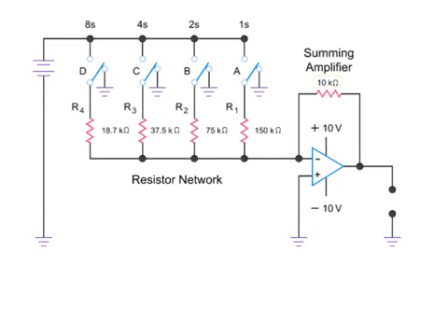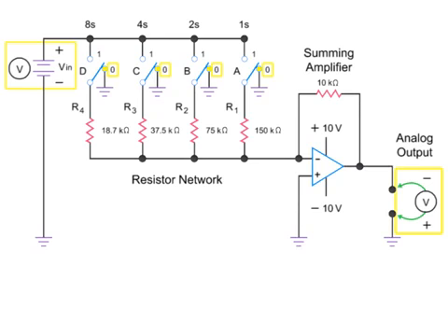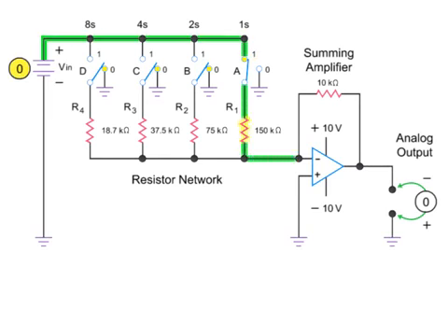With all switches in the 0 position, the input and output voltages will be 0. However, when switch A receives a logical input of 1, it toggles to the closed position. This results in an input voltage to the op-amp of 3 volts.